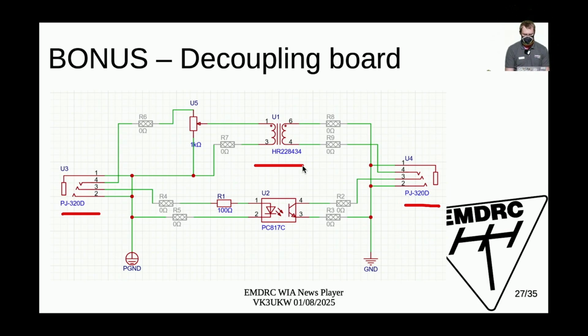That's an isolation transformer that's got the coils in it, especially for speech up to 3000 hertz, which you've got typically in speech. It's optimized to transmit those frequencies and basically reject everything else. And obviously, because it's a fully isolated transformer, it also rejects any DC currents.